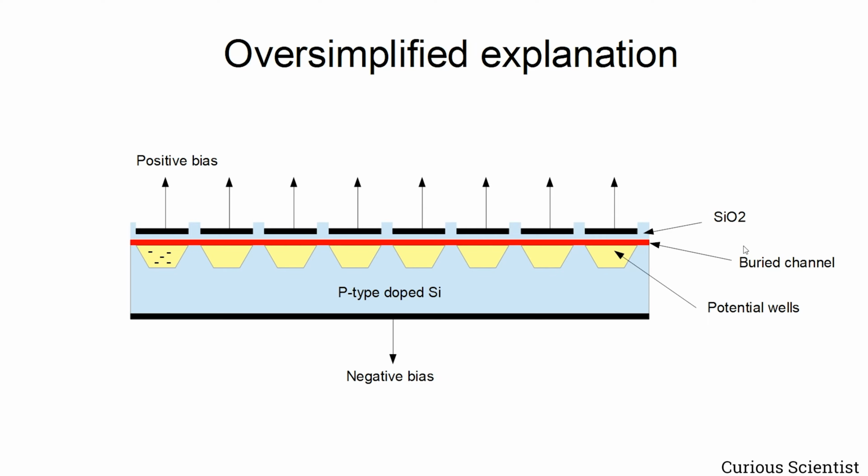And how this is moved out is basically we just apply some clock signal, so the clock signal will control the sequence of the change of the bias on the different gates. And then with this clock we will just move out the charge, so there will be a certain frequency at which this is moved out, and we will actually create this frequency, and we will take care of the rest of the things.